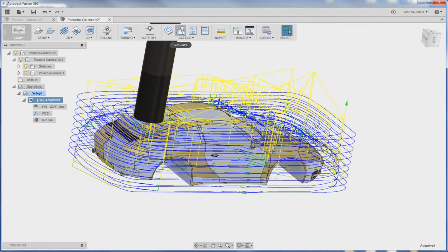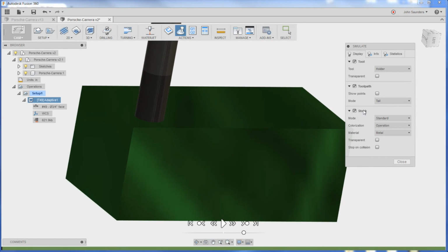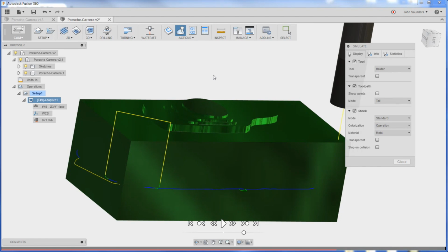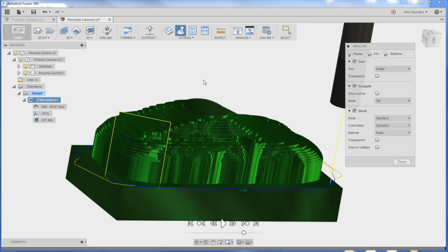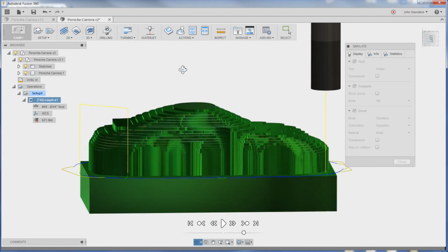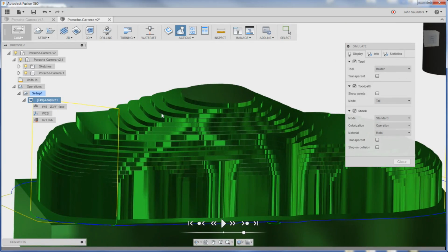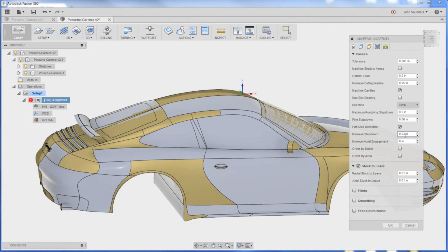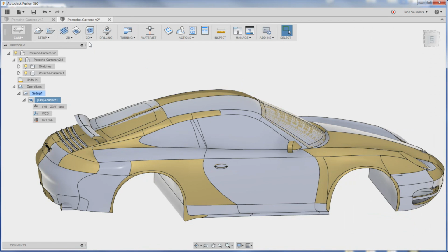I like to do sim a lot, so in simulation, I'll click fast forward just to go to the end to see what we get. And we're just roughing stuff out here. Pretty cool. If you wanted smaller stair steps right there, the most important variable that I'd encourage you to focus on is this minimum step down and fine step down. Those are the 2 big ones there. Now all you got to do, God, this is amazing.